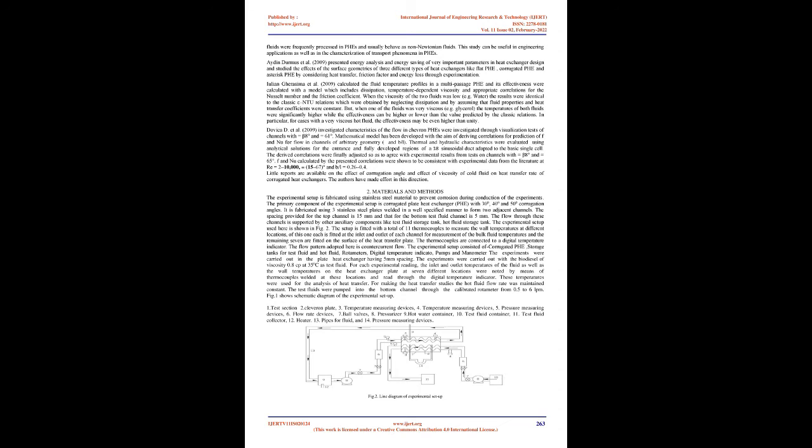A rheological study was carried out in order to characterize the stirred yogurt flow behavior, evaluating its dependency on both shear rate and temperature. A shift in the temperature dependency was evidenced at 25 degrees Celsius. It was also shown that the material shows complex flow behavior, changing from a Bingham fluid to a power law fluid at shear stresses in excess of approximately 6.7 Pa. As regards the heat transfer behavior of the non-Newtonian stirred yogurt, a correlation for the convective heat transfer coefficient was obtained that reveals the large effects of the thermal entry length, due to the high Prandtl numbers and to the short length of the PHE.